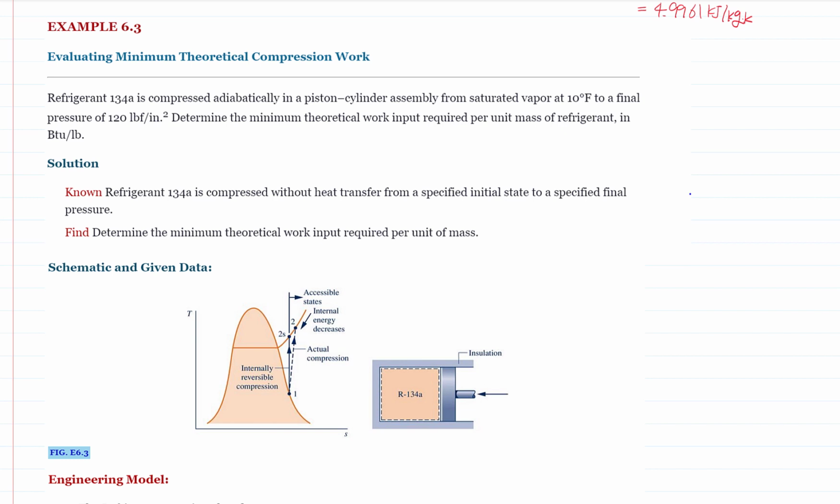So we take the refrigerant as the system. It is a closed system as there is no mass transfer across the system boundary. And the piston cylinder device is stationary, so we neglect the kinetic and potential energy change during the process.